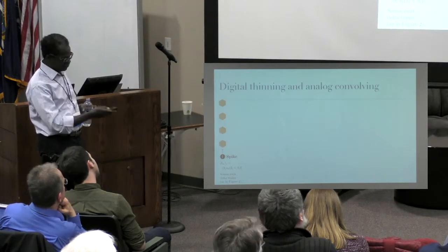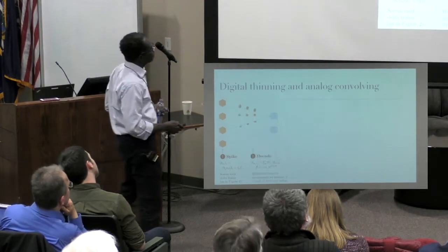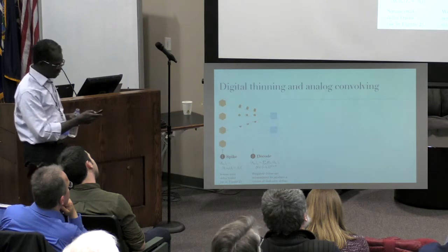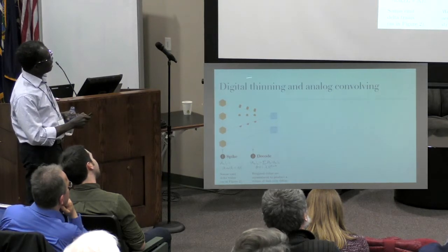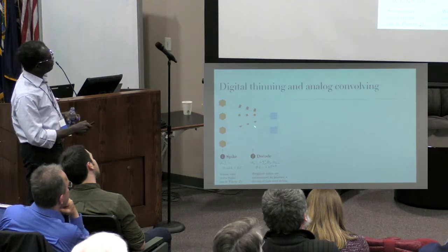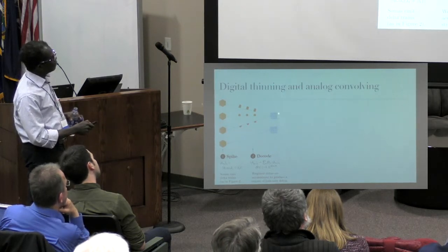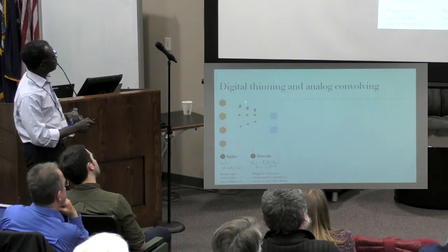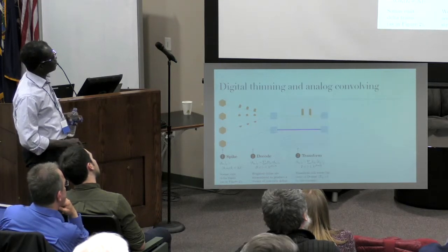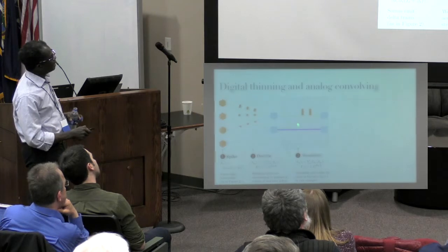So what we do in BrainDrop, which is what the chip is called, is we replace the merging operation that happens here with what we call accumulative thinning. It's a way of basically letting, if you want to apply a weight of 1/3, then you let every third spike through on that channel, but you don't change the area. And so basically what it does is it thins, but then it restores.